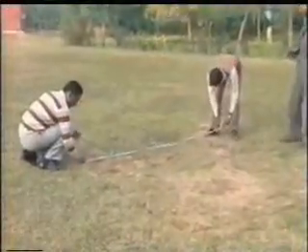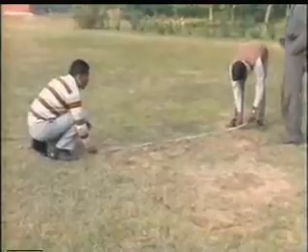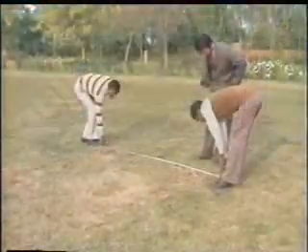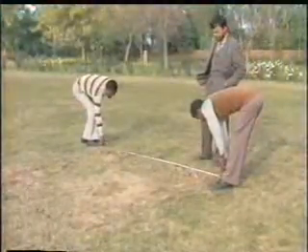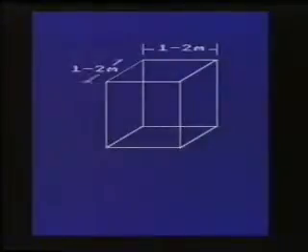With simple and careful excavation, highly undisturbed hand-cut soil samples may be obtained. For this purpose, a pit about 1 to 2 meters in length and breadth is excavated to the desired depth.